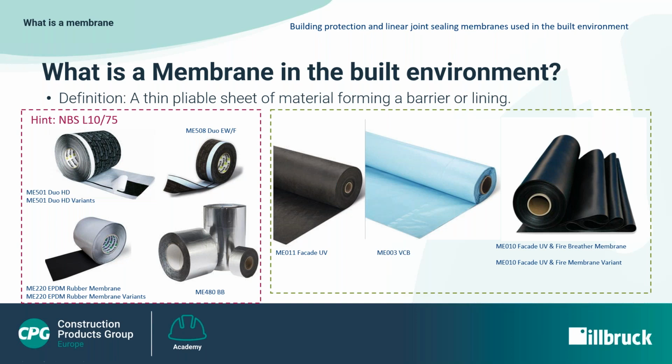Membranes are sometimes backed with a high-strength water or moisture-resistant self-adhesive. Some membranes require a separate paste adhesive or a tape before they can be applied to provide a permanent bond. Some membranes are equipped with preformed profile gaskets on the leading edge, but require an adhesive to bond the trailing edge. If a paste adhesive is required, it should be compatible with common substrates for ease of use, and a responsible manufacturer provides a range of alternative adhesives and primers to deal with difficult circumstances and varying substrates.